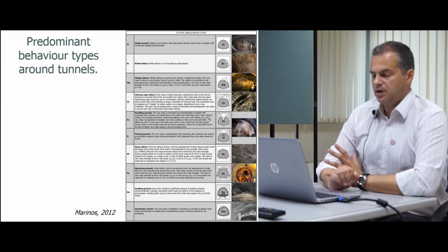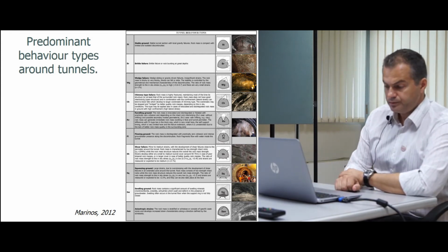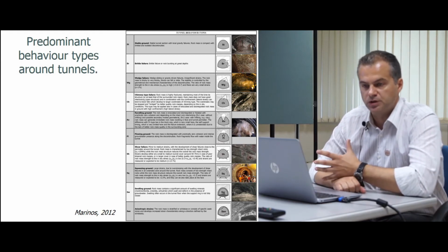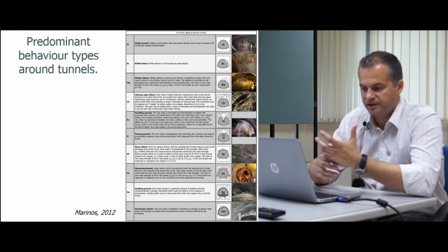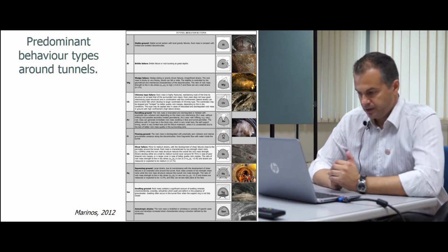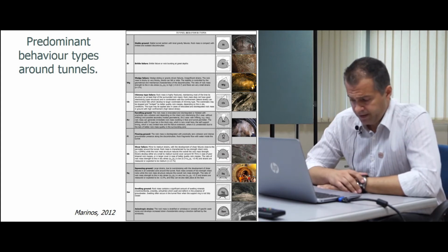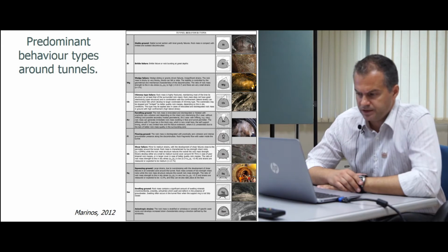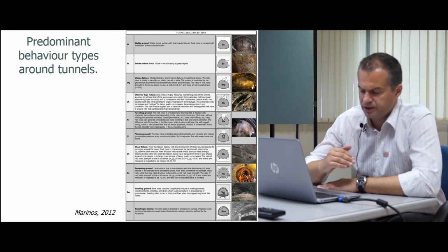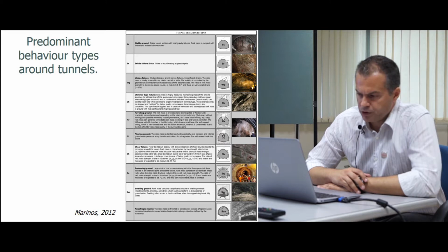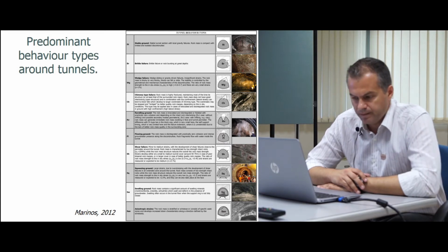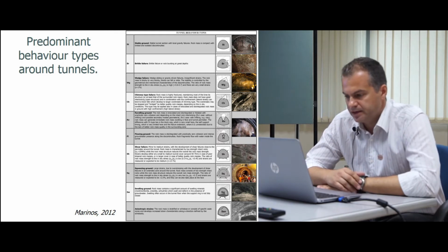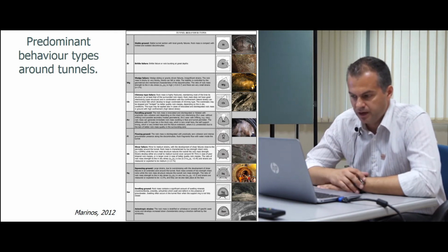Of course, it is not only due to the rock mass conditions, but also due to the tunnel geometry and the diameter of the tunnel, and the direction of the discontinuities in relation to the axis of the tunnel. So not only the rock mass quality governs this tunnel behavior type.